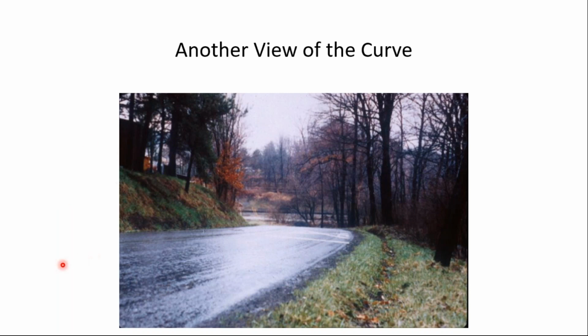But this was sort of an unfortunate perfect storm of a number of issues. The roadway was banked the wrong way, so it was certainly not going to resist the lateral forces. You had a bleeding pavement. You had a roadside that was lined with large trees. You had a rainy night, and you had a driver who had never been on this road before and probably was going too fast for conditions.